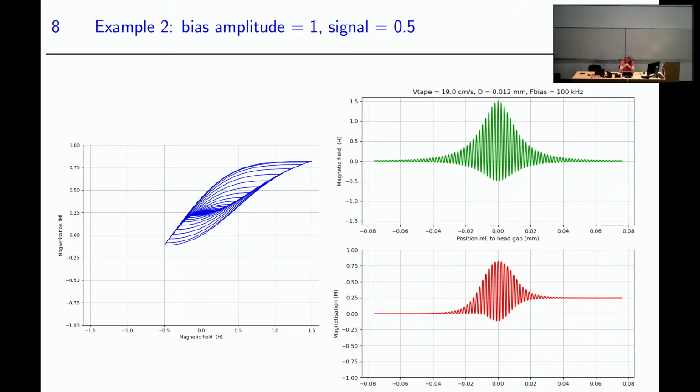First of all, full marks for investigating in such depth. Having been a victim, I regard myself, of tape machines right the way back to the 1960s, and the standards there were just unbelievably poor. And I've been in the position of testing machines, and on some of them, with the old mu metal type replay heads, you could actually watch the HF response degrading as the tape was playing, just on one play.